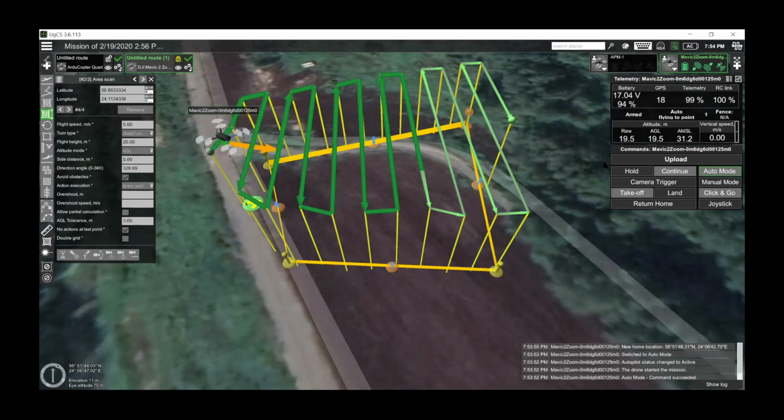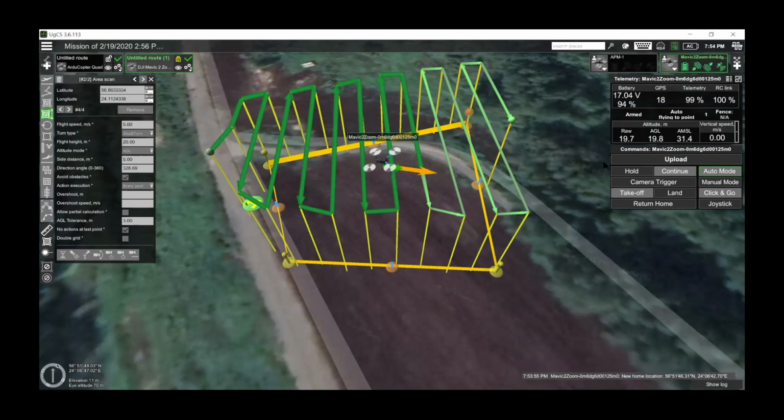So I see that there was the question, what is Rangefinder? Rangefinder is how the laser altimeter is called in the Ardupilot glossary. Currently, Ardupilot, as far as I know, doesn't support other kinds of rangefinders, for example, those based on radio or something like that. So only the laser altimeters are an option now.